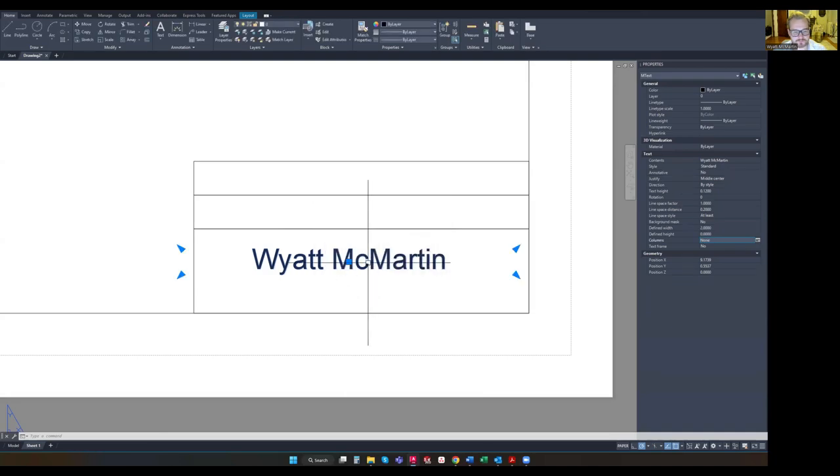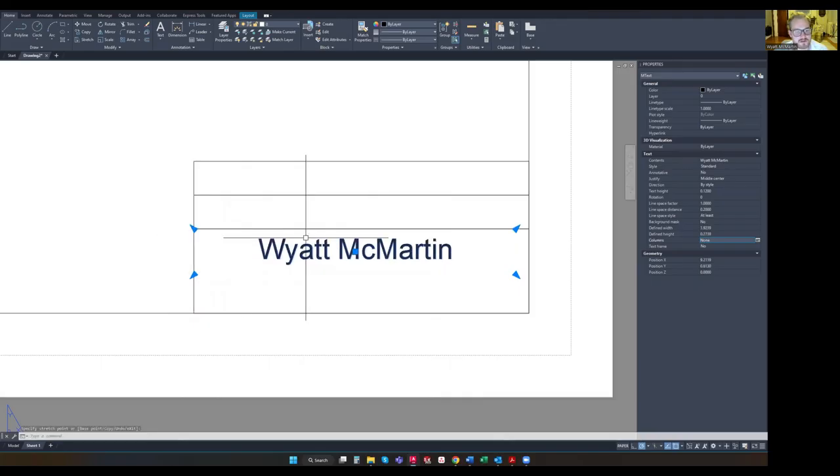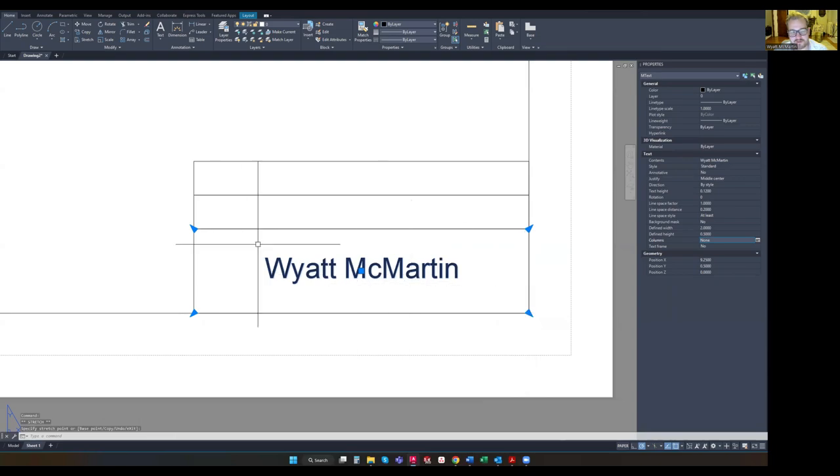Okay. When you do that, now you have these little points that you can click and drag. So I'm just going to click once and release, and then I'm going to snap that point. You can't really tell that you're holding it other than you clicked on it and you know that you're holding it. But I'm just going to click it to the top left corner of the larger, the 2-inch by 0.5-inch rectangle. And then this bottom right snap point, I'm going to snap that to the bottom right. And now I have a perfectly centered